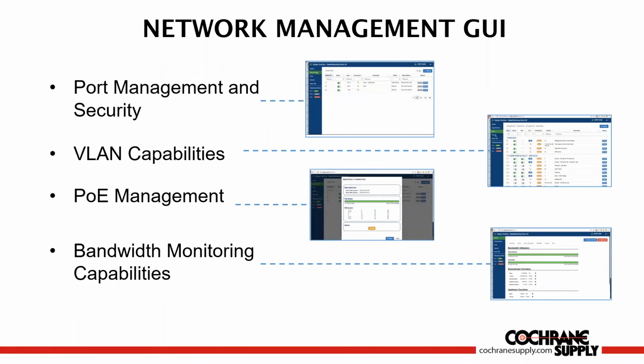Now, I talked a little bit about a graphical user interface. So when you're selecting an OT network and you've got this network management switch, which is quote unquote the front end for the OT network, and now you've got the other switches out in the system, you want to make sure there's a graphical user interface so that you can see what's going on with each switch. So in other words, if I plug in say an 8-port switch, I want to be able to view every port in a graphical user interface similar to what you're seeing on the screen now,